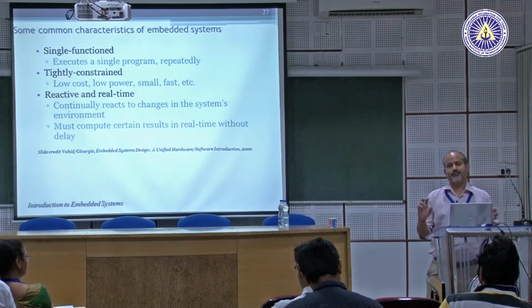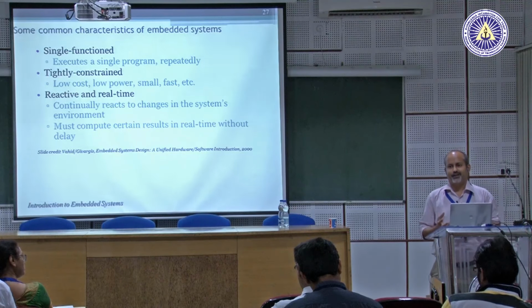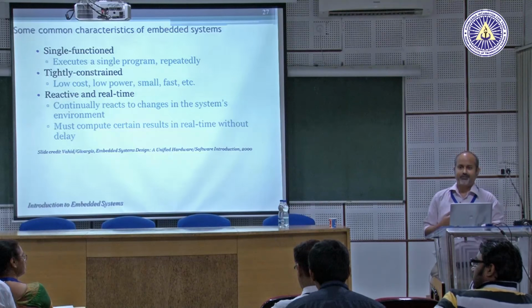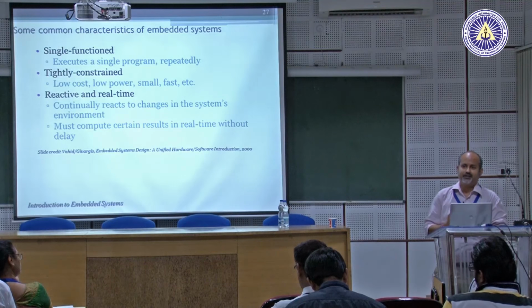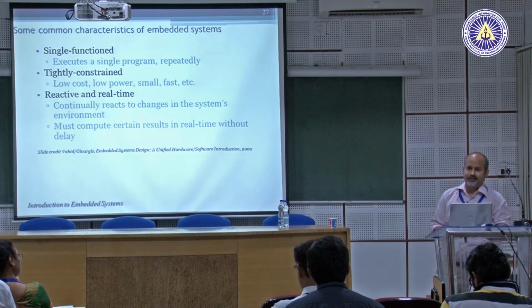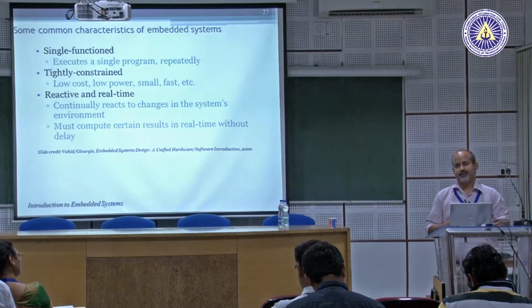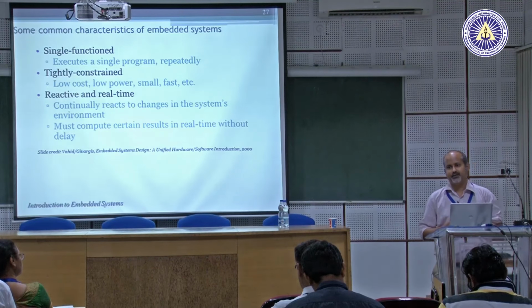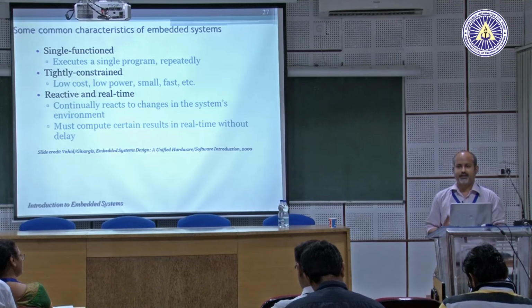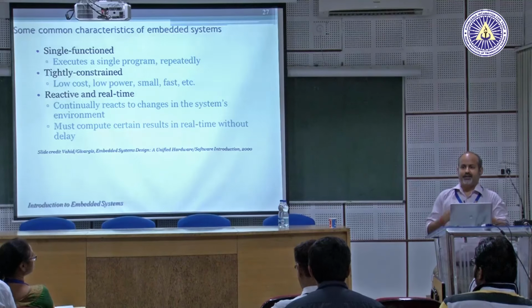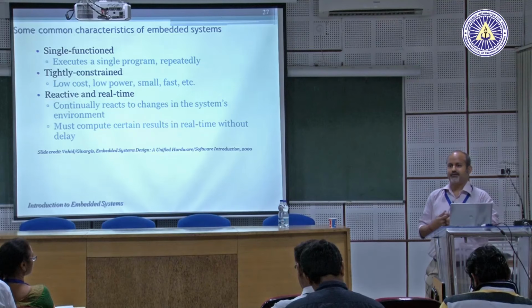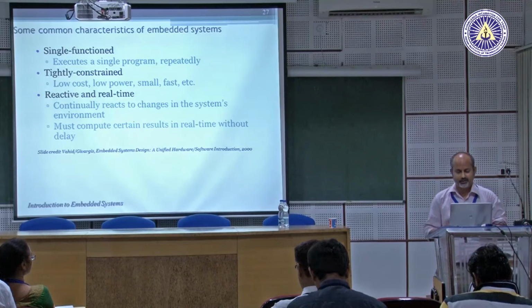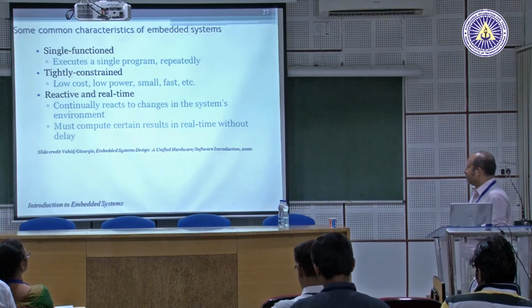You could have taken a much larger, much more powerful processor and integrated all these functions, but that's not normally done. The reason is that it gives you much better fault tolerance. For example, if your air condition unit is in the same processor as your brake, and your air conditioner doesn't work, maybe your brake will also fail, and that's not good, right? So you want to separate them.